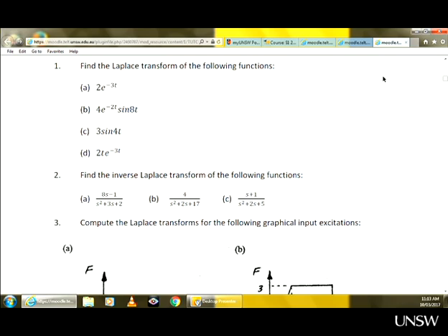Now, what is the input? Why would the mercury move? Because there is an external temperature. So the temperature starts the process, and we are describing that process. So that external temperature is the input. So here theta and theta zero and everything about theta are the temperature. Is theta temperature? Yes. Temperature of the hot water.